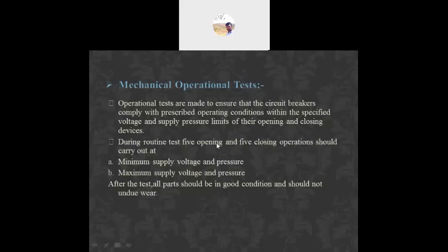Next, during the routine test there are 5 opening and 5 closing operations. The operations should be carried out at maximum supply voltage and pressure, and at minimum supply voltage and pressure.